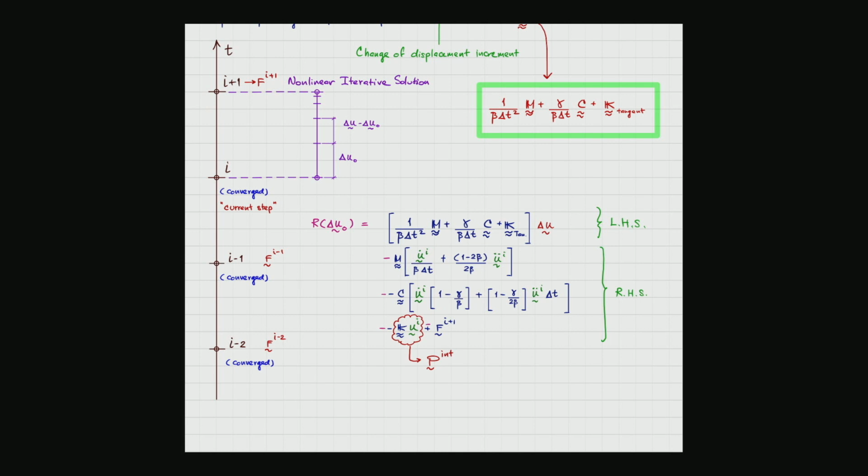The new mesh is going to absorb the information which is obtained from the previous part of the analysis. So you're going to have the sets of stress and strain in the given new elements, and you change from one scheme to another scheme. So you change from the coarse mesh to the finer mesh.